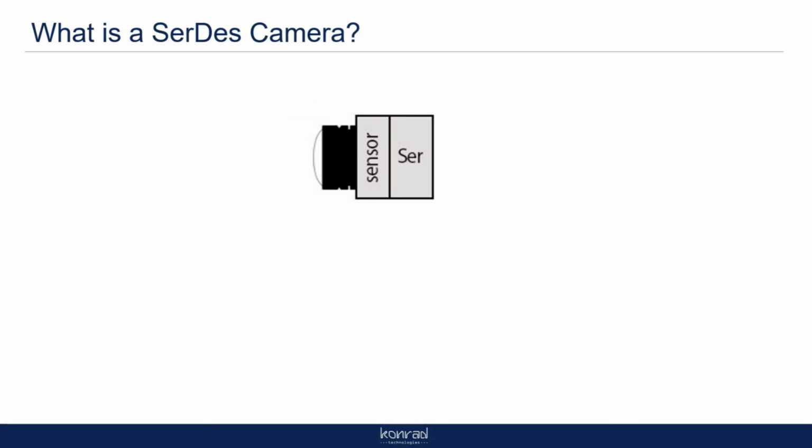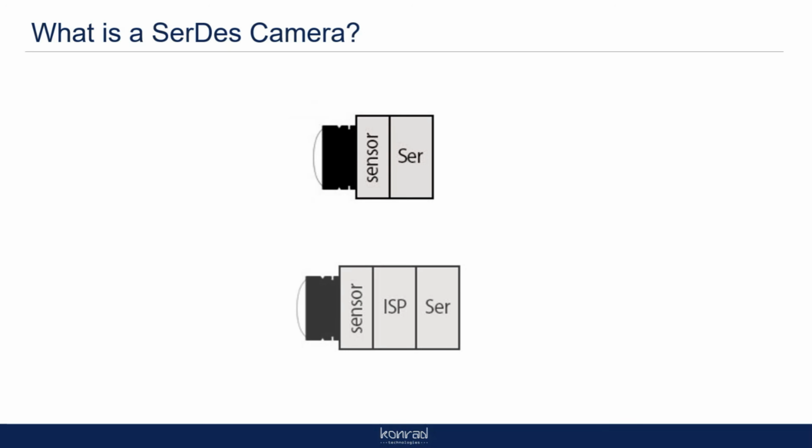In order for these cameras to be used in robotics applications, which are some of the projects I'm currently working on, or in automobiles, you need to take it to a different physical layer. So they put a serializer, shown here as the SER, on the camera. Some of these cameras do a little bit more. Mobileye is the biggest manufacturer of this type of camera.